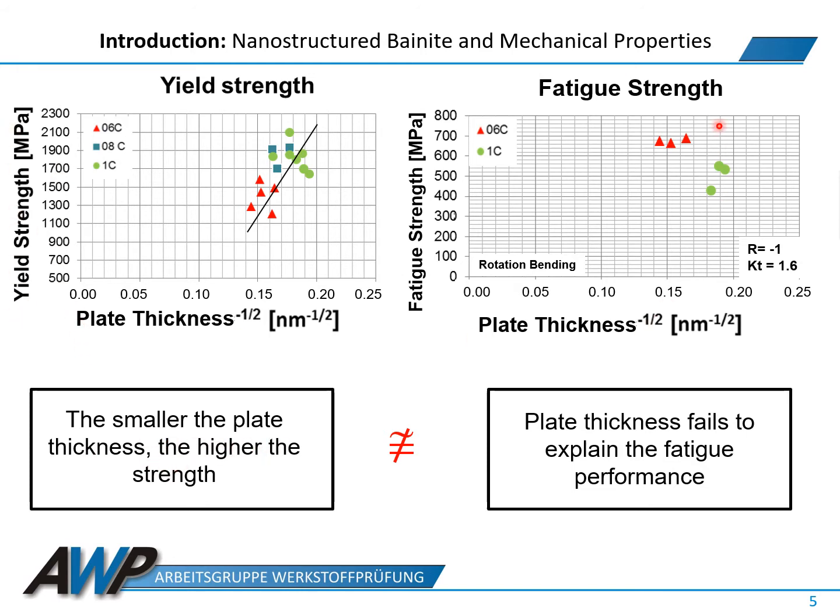However, on the right-hand side, the plot of fatigue strength against the plate thickness fails to explain the fatigue performance. Considering that the in-service durability of a component is limited by the fatigue performance rather than the static properties, the motivation for research on understanding the relationship between the microstructure and the in-service properties can be readily understood.